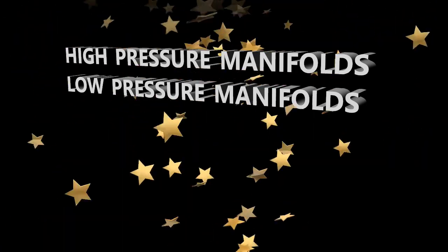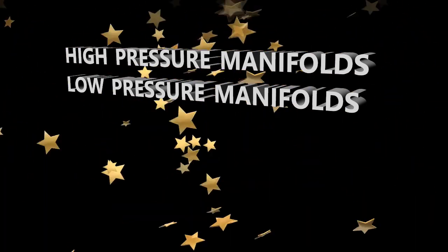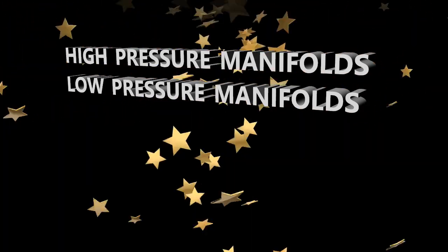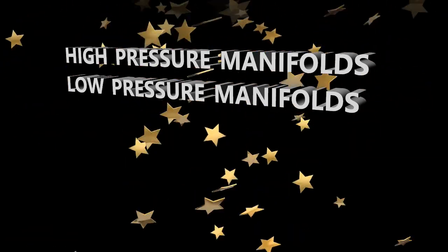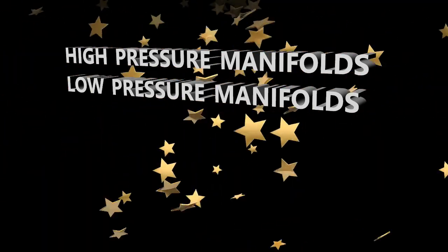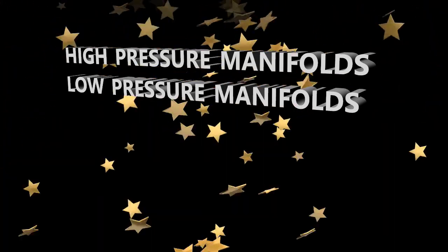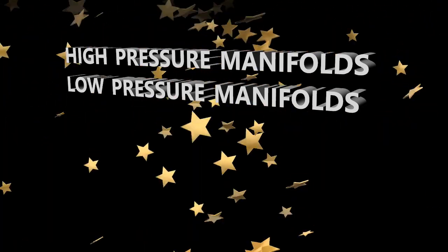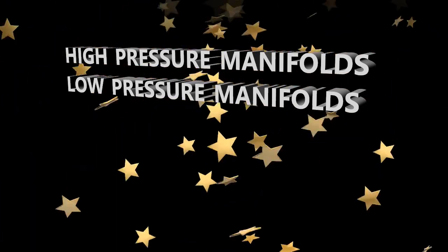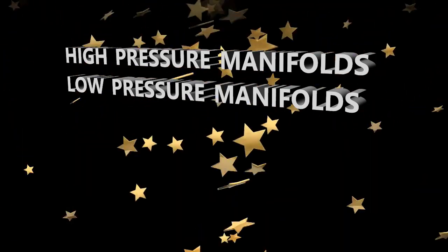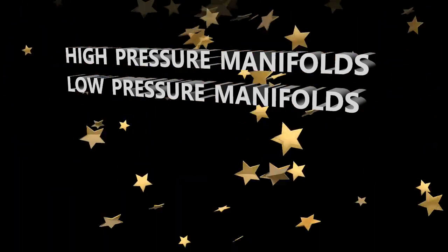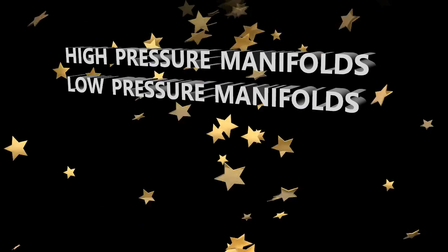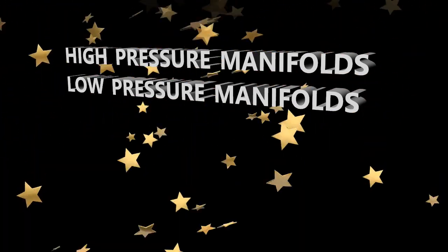So when we're talking about the temperature switch, that is set to operate at a certain temperature. Let's just do degrees Fahrenheit: at 203 degrees plus or minus about 4 degrees Fahrenheit, or if you want to look at it from a Celsius standpoint, at 95 plus or minus about 2 degrees Celsius. It's set to operate there, and it's set to reset if the fluid temperature goes below 88.4 degrees Celsius, or 191 degrees Fahrenheit.